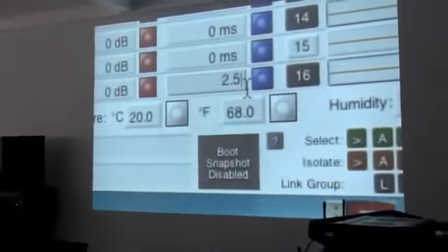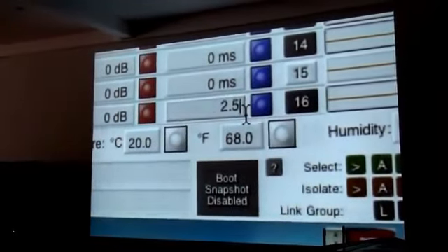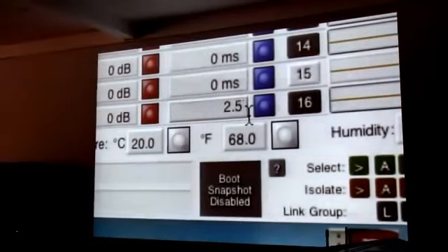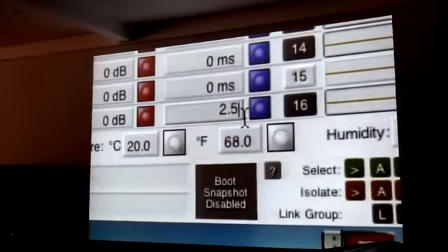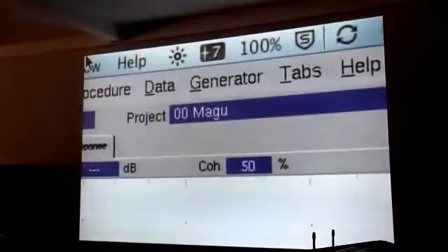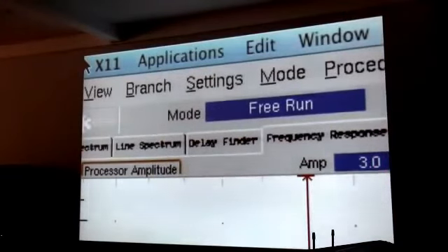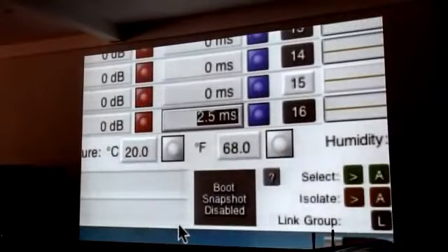So, what happens if the delay is 2.5 milliseconds? How much is that for the 100 Hz period? 90 degrees. Okay. At 90 degrees, the summation is 3 decibels. So right now you know two audio signals with the same level, same polarity, correlated with a 90 degree difference give 3 dB of summation.